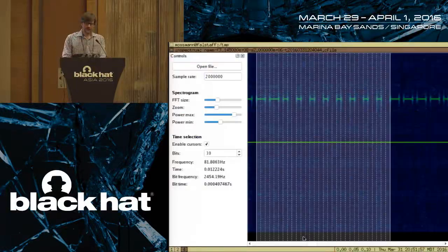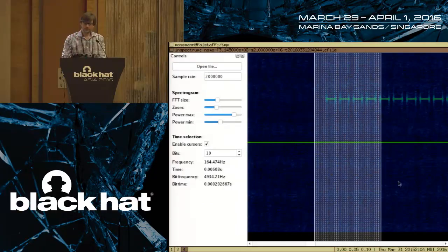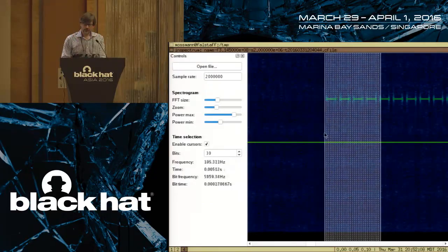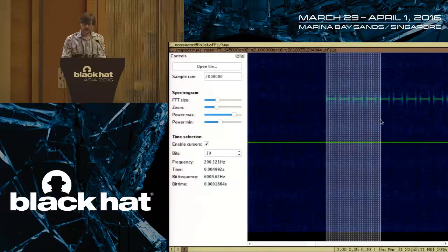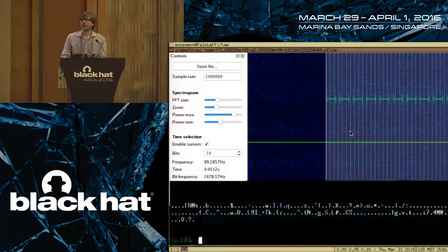If we look back in Spectrum, at the beginning of a packet, what we had was not 1, 0, 1, 0, 1, 0. What we have is, in fact, well, I don't have this quite set up right, but what we have is 1, 1, 0, 1, 1, 0, 1, 1, 0. We have a waltz instead of a two-step, and that is not going to satisfy the Yardstick 1's notion of what a preamble looks like.